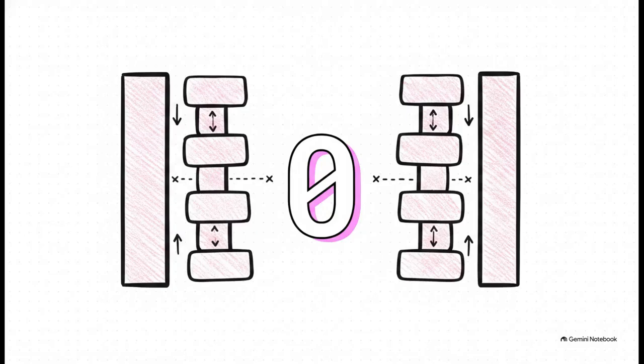But before a wall even moves a millimeter, we have to talk about zero, specifically absolute zero lateral strain. We call this the at-rest condition. Just imagine an element of soil deep, deep underground. It deforms vertically under its own self-weight, sure, but its lateral strain is absolute zero. Why? Because it is completely prevented from deforming laterally by the infinite extent of the soil surrounding it. Basically, it's locked in place by adjacent restraints.